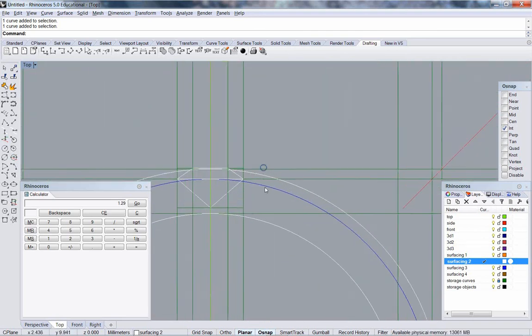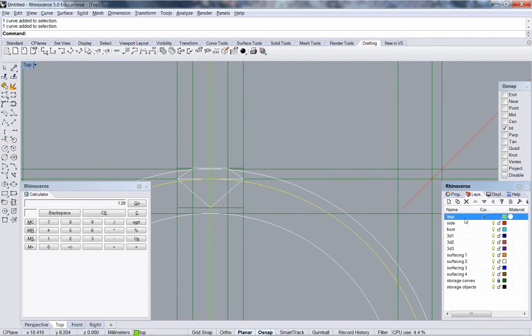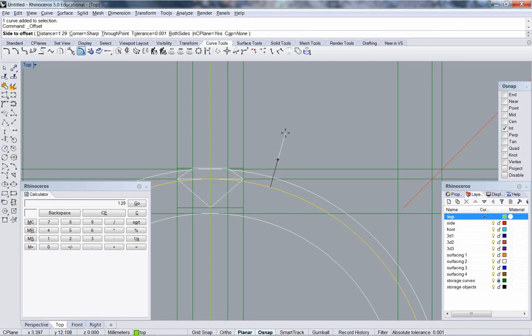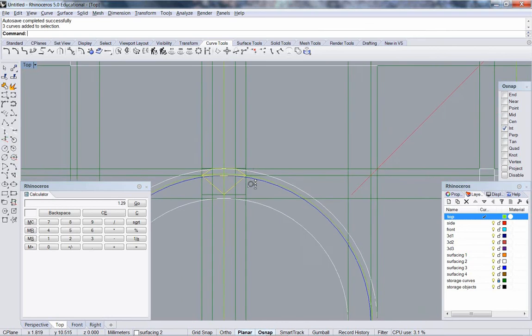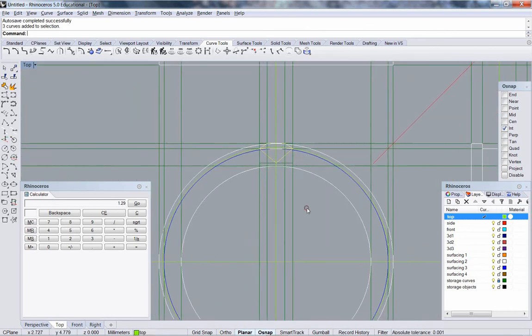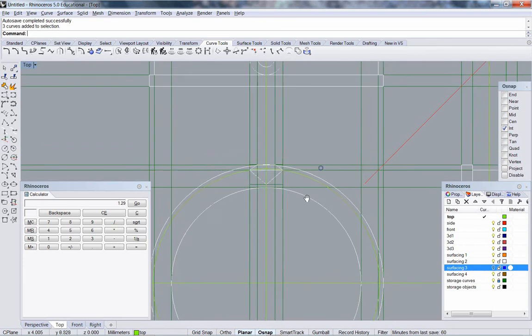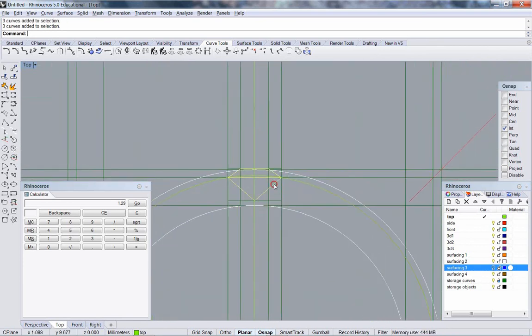I'm going to draw a construction line, a reference line. Okay? To catch the edge of that girdle, because that's the edge that we need to actually space our stones. And the next command we're going to use needs that curve to work. I'm going to go ahead and turn off our tray, our hidden line for now, so we don't get them confused.